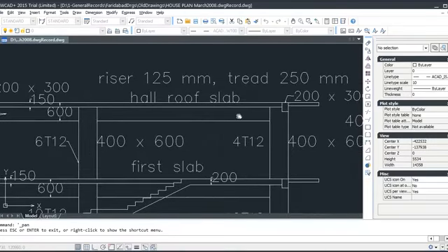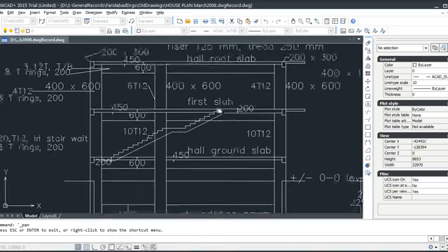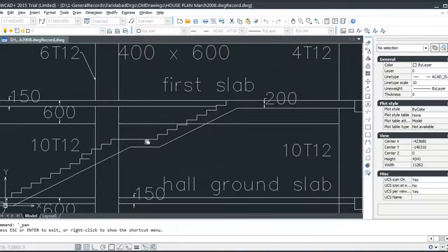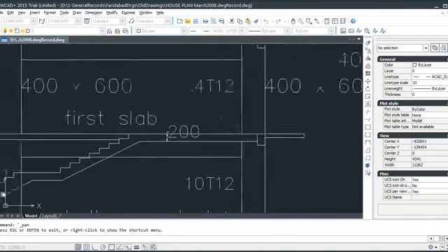And beams cannot be cast separately. Beams are to be cast with slab, and that's framing we do. And this slab of stair can also be cast. What actually is done: first flight and this landing are cast in one go. Generally these are cast in one go with steps. Of course, don't forget the steps. The steps are a very important part.